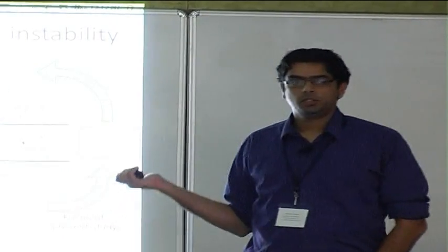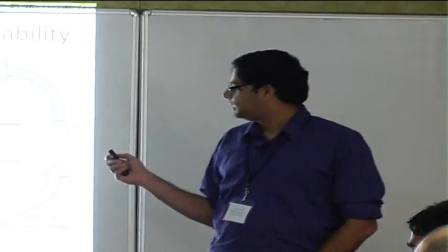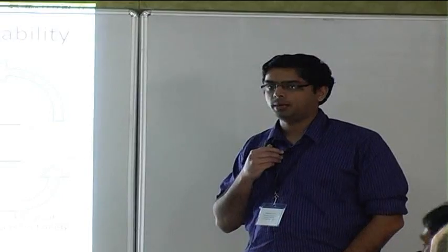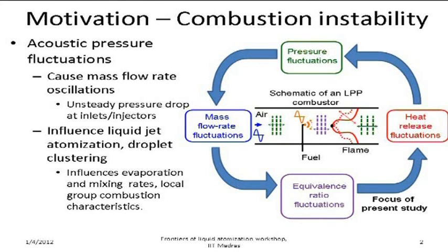So the motivation for doing this work is combustion instability, which is very familiar to everybody who works with gas turbines. The main driving mechanism for combustion instabilities is coupling between acoustic modes and other heat release response in a combustor. So let's say we have a cartoon of a gas turbine combustor here, and we have a fuel injector here that's putting a spray out that's vaporizing completely, and eventually you have a flame that is completely sitting in a gas phase flow, a single phase flow, but with fuel and air.